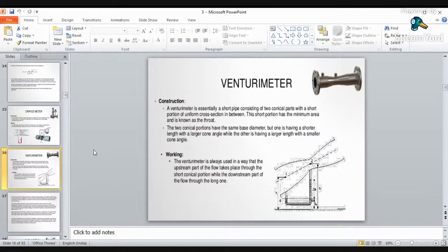Now, the venturimeter is used when you have a large volume of liquid and gas phase. But there are a few demerits or disadvantages for the venturi tube: it is highly expensive, it requires considerable space, and we cannot alter the measuring pressures beyond a maximum limit or maximum velocity. Once the maximum velocity has reached its ultimate point, you cannot measure the discharge with that venturi tube.